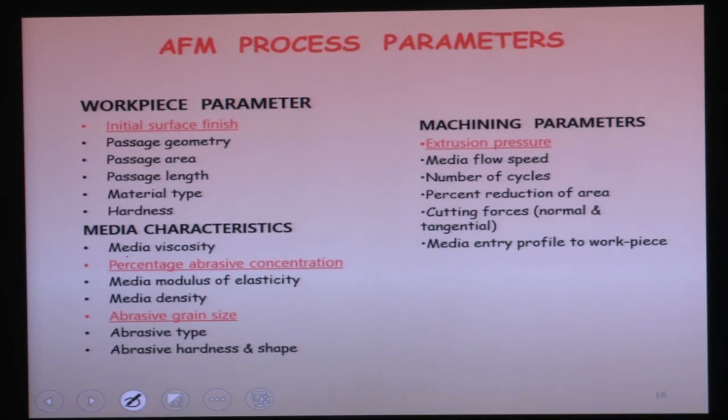Media characteristics like medium viscosity. The viscosity of this polishing media is the main thing. For different hardness of the workpiece material, you have to change the rheological properties of the media. You change the rheological properties by changing the viscosity of the media, and so you can polish workpieces with different hardness.